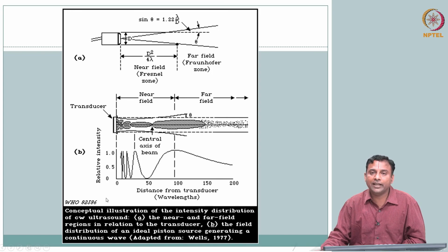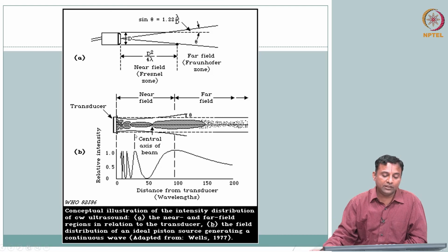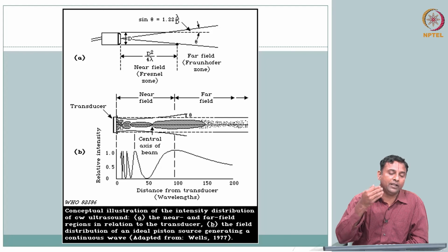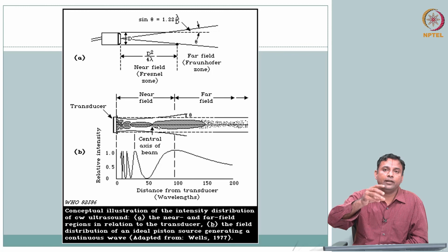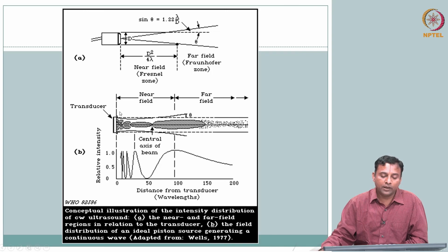So the idea is we need to spend a little more time on this. Depending on this beam pattern, when I send the pressure wave, this is how it is going to insonify the region. What I am going to get back as echo is based on what is hitting at that location, the impedance mismatches. So it is important that we understand the different beam patterns, how we define this beam pattern, and how we get a handle on it.